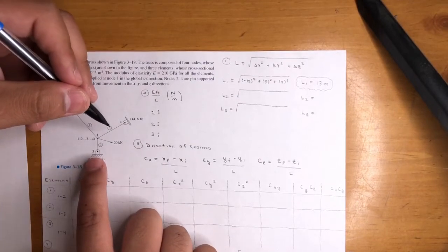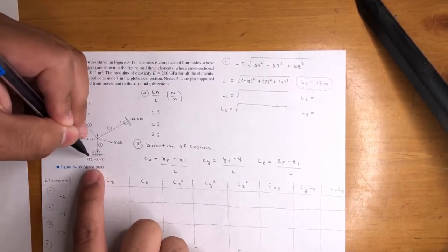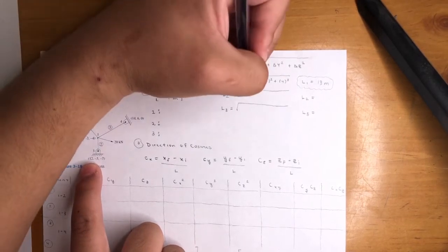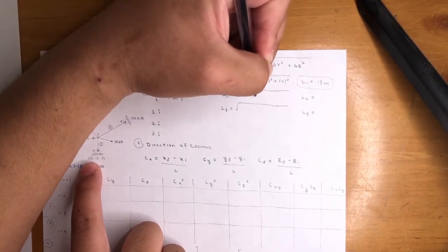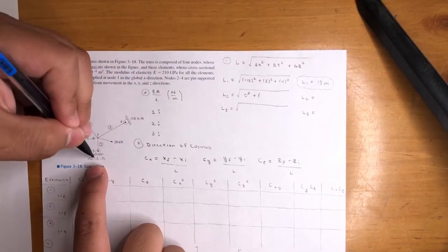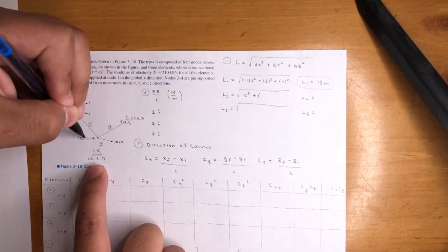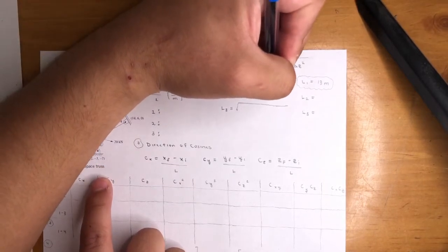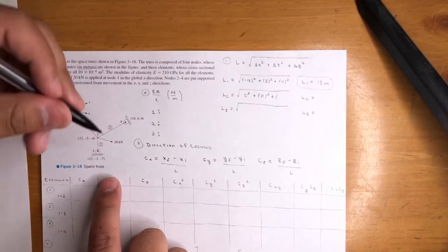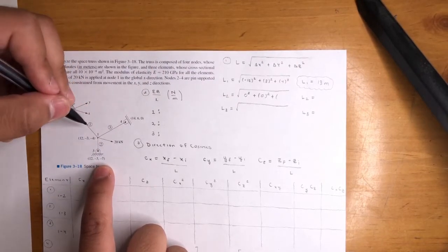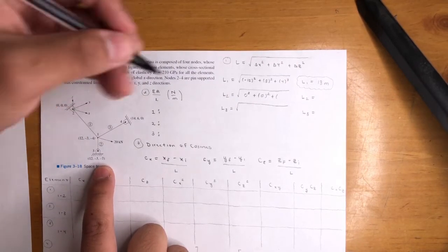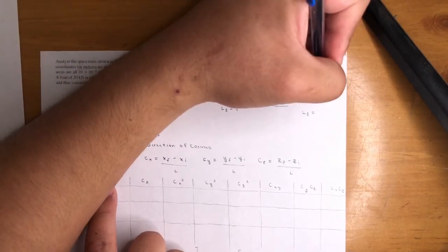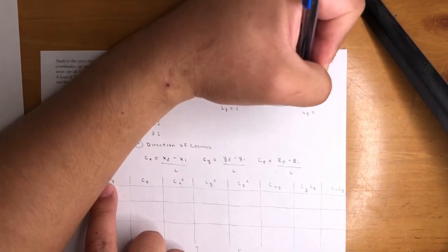Same thing for element 2, right? So we know final minus initial, so 12, the x component, 12 minus 12, that's gonna be 0 squared plus, what else? Negative 3 minus negative 3, which is negative 3 plus 3, which is another 0 squared plus, last one, negative 7 minus negative 4, that's negative 7 plus 4, that is negative 3 squared. If you do that math, you'll get 3 meters for length 2.